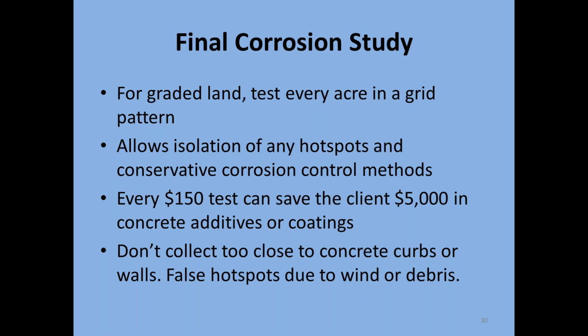It may just be remnants of the concrete mix, powder, something, that got into the dirt and kicked up the soil's salt content, and maybe lowered its resistivities. But mainly it's about salts, the water-soluble salts. So try to stay away from those types of areas, just to not get these false hot spots, basically.